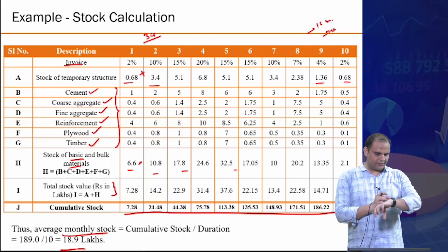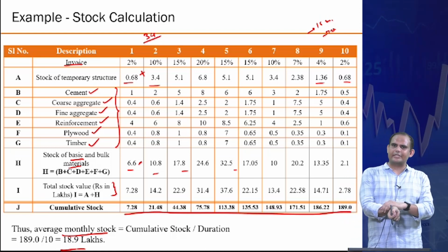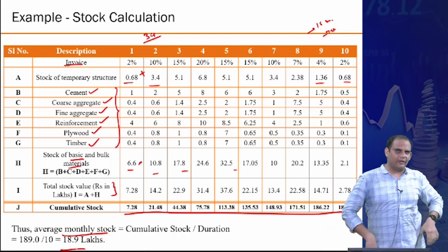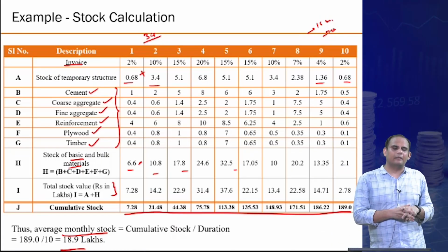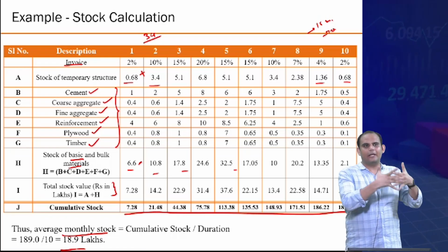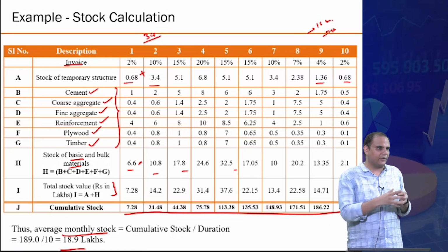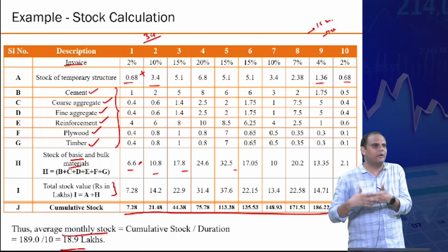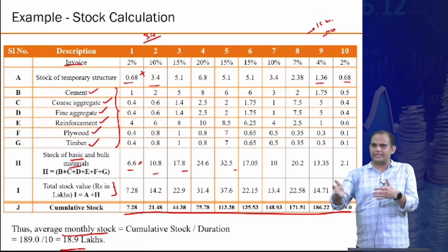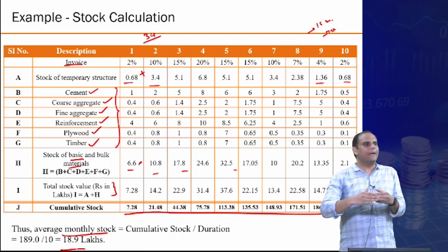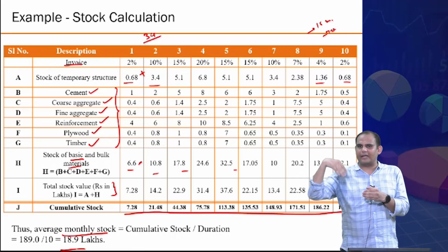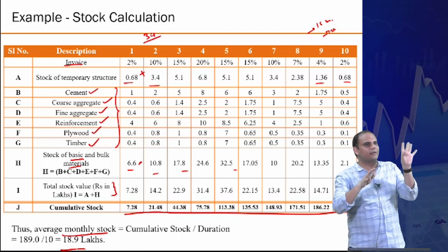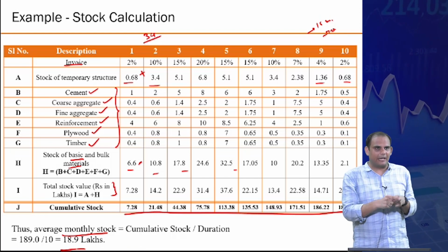Why do you need this estimation? Do you know the concept of working capital? What is working capital? So essentially your working capital is what happens in construction. You are incurring cost on a daily basis, right? Because if you are constructing, you are consuming materials, you are consuming the labors. You as a contractor need to pay the labors perhaps daily, maybe much more frequently, compared to what you are getting from the client. Client does not pay you every day. Client does not pay you, okay, today you did so much work, let's pay you the money. But labors you might have to pay every day.